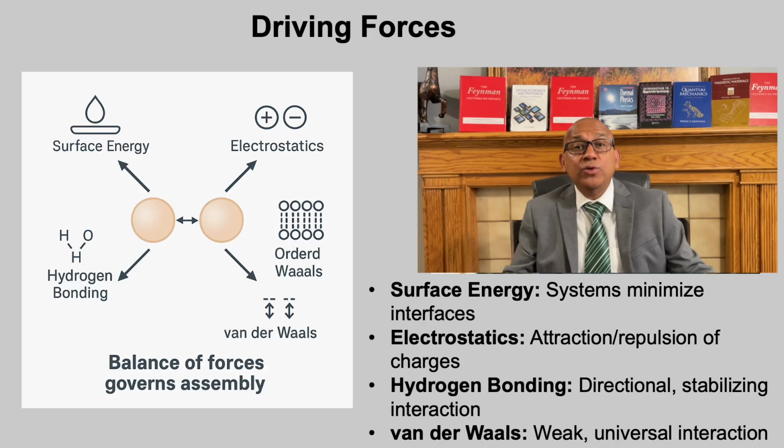Several fundamental forces drive self-assembly and bottom-up nanofabrication. First is surface energy. Atoms and molecules arrange to minimize high-energy interfaces, leading to phenomena like micelle formation and thin film growth. Electrostatics govern attraction and repulsion between charged species, strongly influencing colloidal stability.